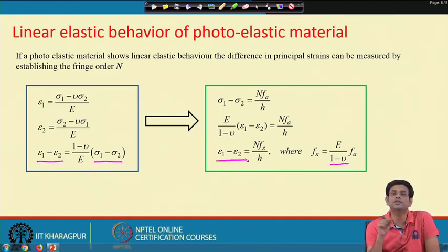Based on this birefringence property, we derive the stress optics law, also known as Maxwell's law, which essentially states that the relative change of the refractive indices is proportional to the relative change in the principal stresses. This stress optics law can also be expressed in terms of retardation. That means, if light propagates in one direction, what is the retardation in the two other orthogonal directions. So we can compute the phase shift between the two orthogonal directions.